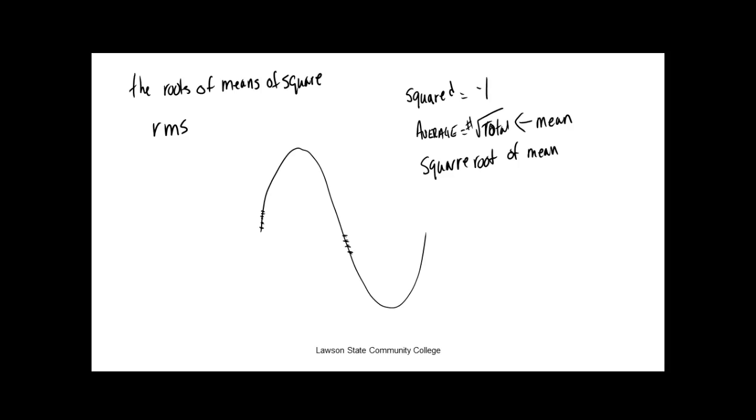So if I took the RMS of a sine wave, so that means a bunch on my positive and equally spaced on my negative, and I squared all those, automatically squared everything, then the negatives would be gone, right? You understand? Then I would average those squares. And then when I got through, I would take the square root of the mean, and that would give me the effects of that. And this is called RMS.